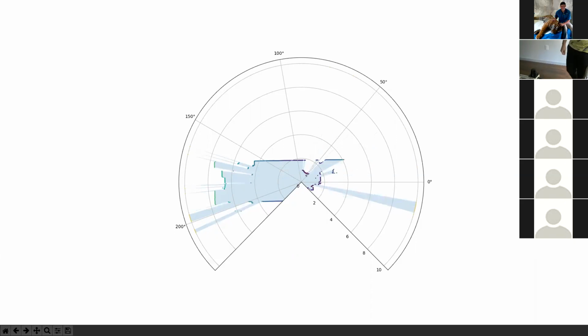You can also see, if you look on the y-axis of this polar plot, there are some data points that are yellow, at the 10-meter mark. The y-axis units are in meters. So you can see the LiDAR's plotted the room, and then there's some points that just go off and hit 10 meters. Jorge, is there a window or something in the room?